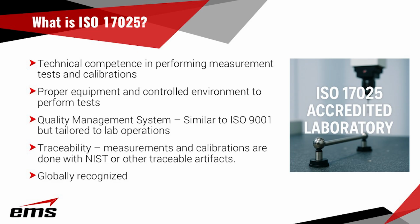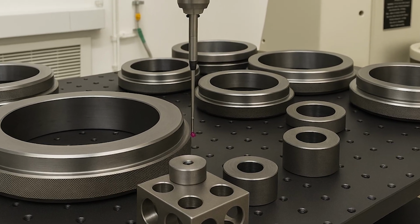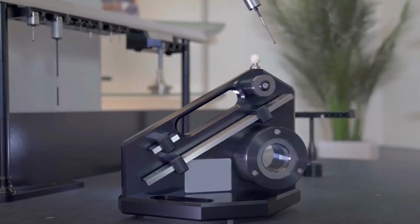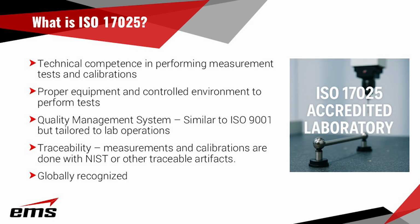They have some kind of quality management system, typically similar to ISO 9001, but specifically tailored for lab operations. They have traceability, which we'll talk about in more detail, but basically the equipment they're using to recalibrate your equipment is traceable back to, typically in the US, a NIST standard, but there's others out there. And that they are globally recognized.